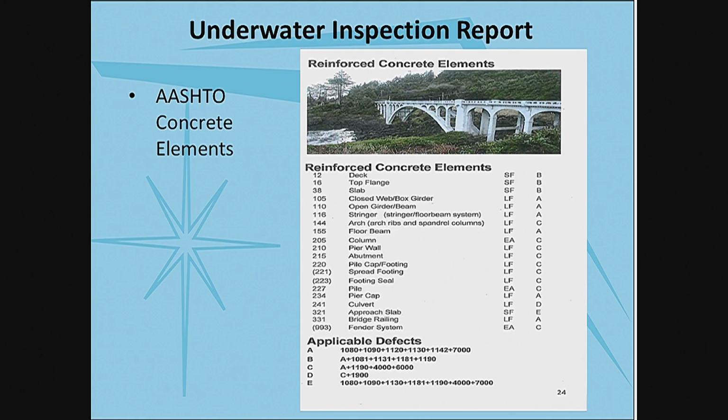Typically, the underwater inspection report will involve concrete members. Now, that doesn't mean to say that we don't have timber, steel, and masonry elements that support your bridges, but the majority of them are concrete elements. And so you'll see on the underwater report these elements and any defects associated with those. So on the underwater report, we take their information, when I say we, our inspectors do, and we marry it with the above water inspection, and then we combine those inspections for an overall rating. We include their elements and their defects,